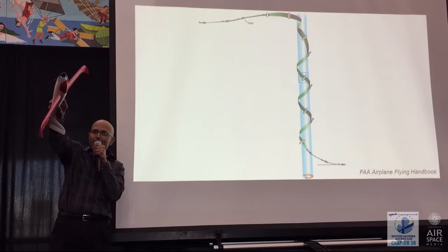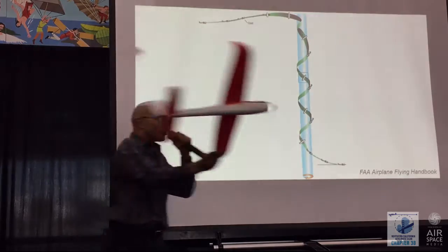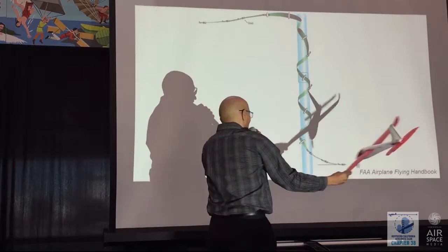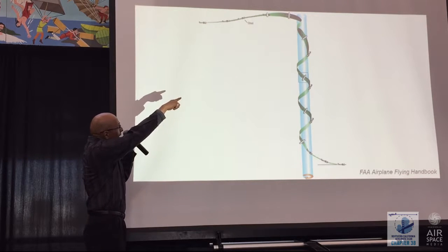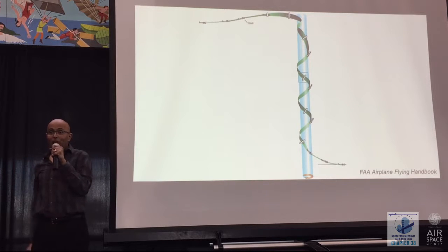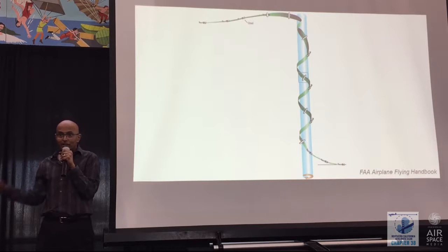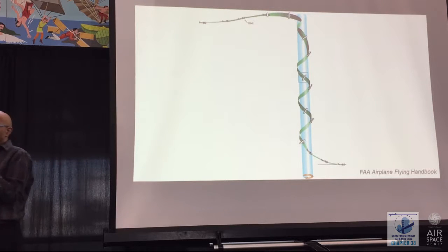That wing drops dramatically, the airplane almost goes inverted. It then goes into a circular pattern, crashing like a stone, and interestingly enough, this is a stable pattern. The airplane will keep doing that unless you do something about it. And the amount of time required to figure out what's going on, and the height that you lose by the time you figure it out and fix it, can be quite significant. So if this happens in a traffic pattern around an airport, it is universally fatal. And very, very dramatic, and people fall into this problem all the time.